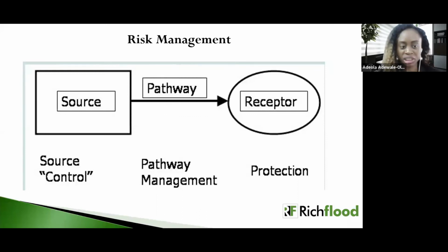And the approaches that we may want to adopt at this stage may include having barriers, such as impermeable, maybe bentonite walls driven through an aquifer, just to manage the contaminant that has already left the source. Because this kind of thing would reduce the flow of groundwater so that the rate at which contaminant is transferred to the receptor would be reduced.